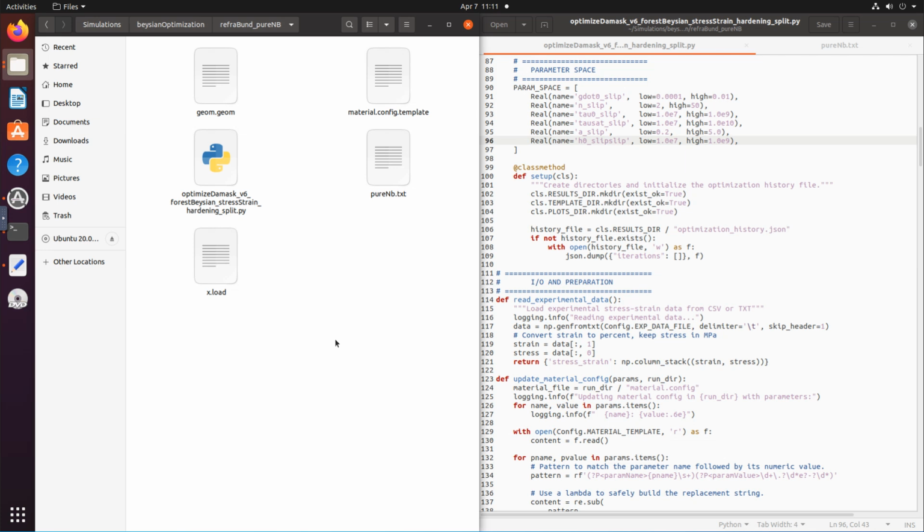So I rule out those things, and now the only thing that remains is the material file and the material parameters there. If my other two things are not correct, although I will identify these parameters, they will also not be correct because my geometry was wrong or my loading condition was wrong. And although I have received a set of parameters, they are not useful.